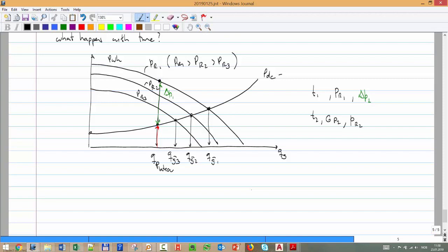And then I come and I check. Note that I'm on the same line. It's the same rate. The only thing now, my delta P2 will be smaller. What do I have to do operationally to make this work? Open the choke.